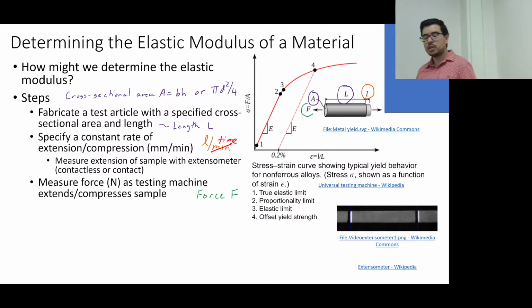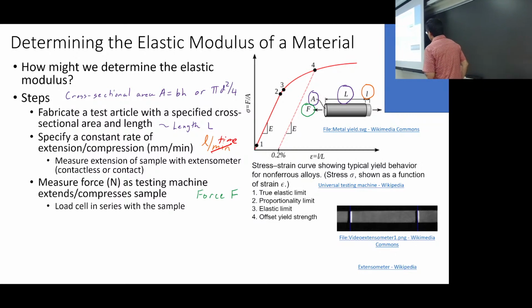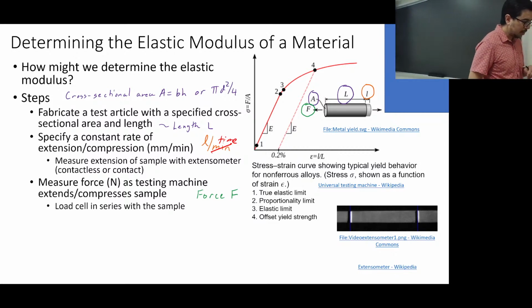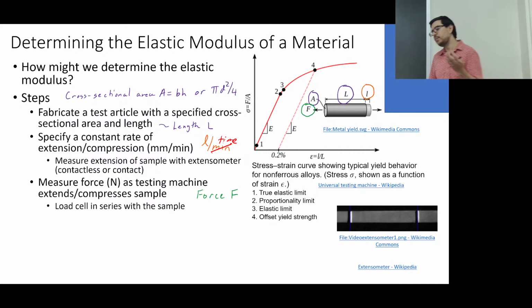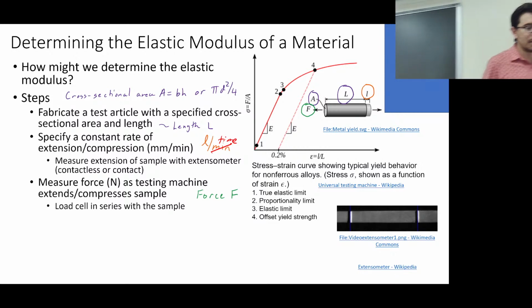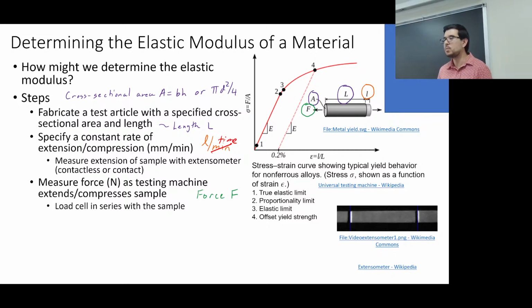You want to use some type of force sensor. There are a whole range of different force sensors out there. Something you may not think about initially with force sensors is that they do have compliance embedded with them as well. Typically, they have to have some type of element that's straining inside of them, like a spring, and they're also doing some type of distance calculation to figure out what the force is.